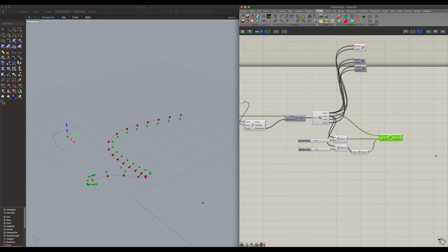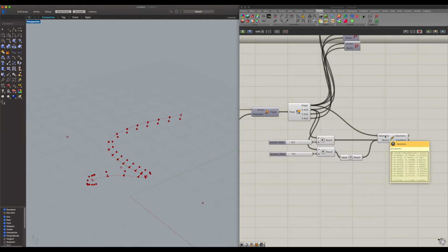And the reason for that is very simple. It's because at every list we want to move 21 points, but here, as you check, for example, the input here, there are 21 points that should be moved with 21 different vectors, but instead of 21 we have 42. That's because we gave the moving factor from the positive vector and the negative, which was also another 21 vectors, into the same input.